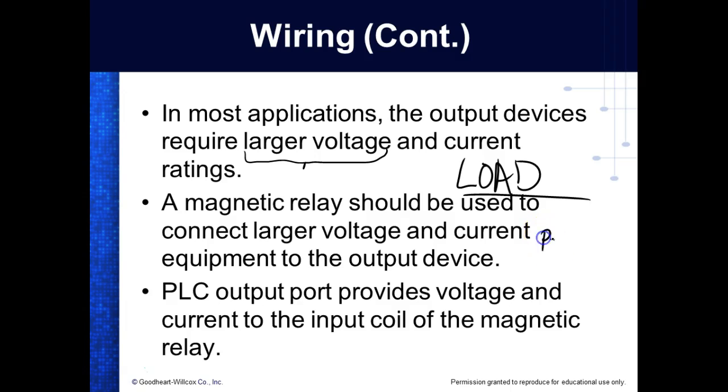So P is equal to, our primary formula is P is equal to what? I times V. So I is equal to P over V. So that means the higher I can make the voltage, the higher the voltage the device is rated at. Now you just can't go out and do it yourself. So every load that we have is specified a voltage. Now a resistor that you ran into in DC, the voltage is not specified. But just about every load in your house has a power rating, even a light bulb. You go out and buy a light bulb, one of the things they give you is what? The watts.